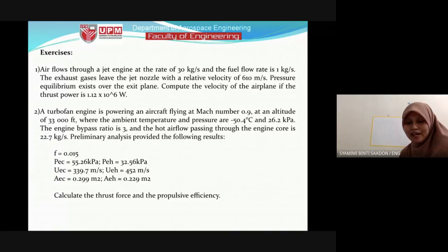And then we have the exit pressure for the cold and hot. Just now, this one is the ambient pressure, and this is the exit pressure. So for a turbojet, normally we have only one exit pressure, like just now, PE and PA, ambient.